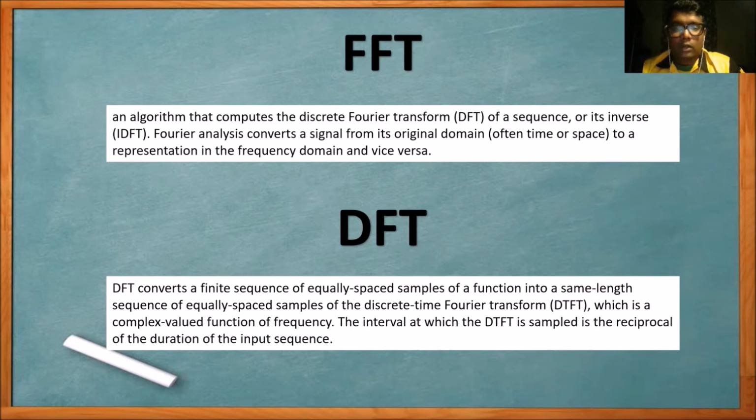It is very common to encode the information in the sinusoid that forms a signal. However, in some applications, the shape of a time domain waveform is not applicable for signals, in which case signal frequency content becomes very useful in ways other than as a digital signal. So the representation of a digital signal in terms of its frequency components in the frequency domain is very important. The algorithm that transforms the time domain signals to the frequency domain components is known as the discrete Fourier transform, or DFT.